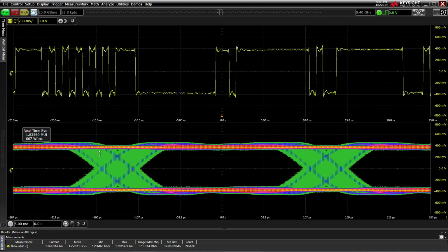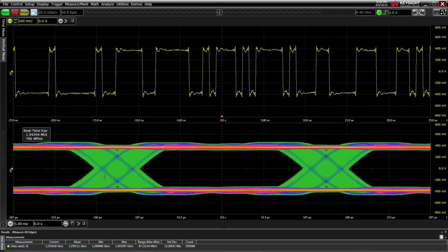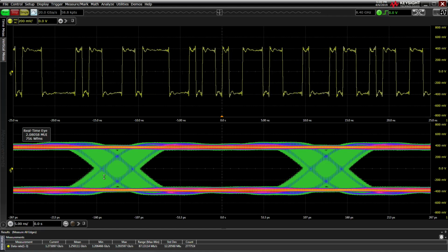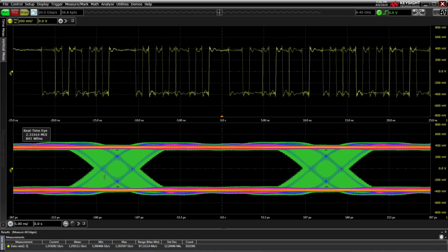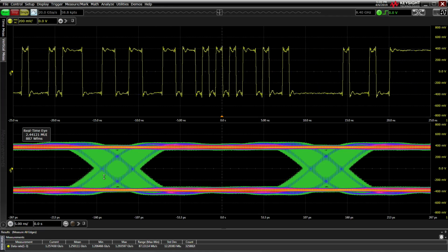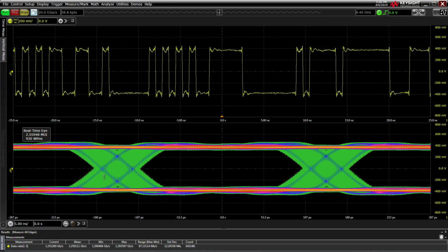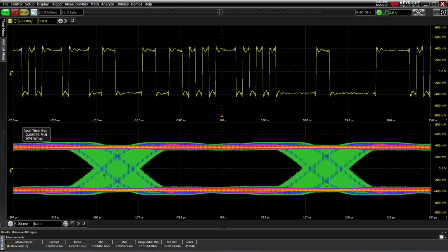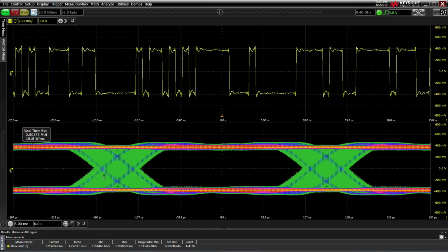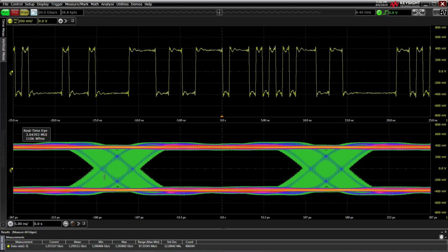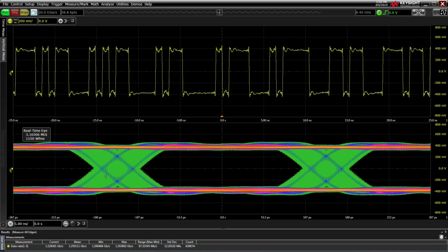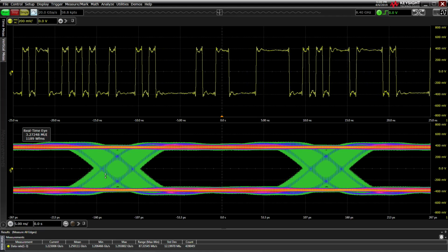But you can clearly see that the jitter can be applied to the signal, and this is a very useful tool to stress clock and data recovery systems to see how they react when they have a particular jitter composition. You don't have to put a square wave, of course, you can put any waveform you want, and that's going to be directly translated to the jitter frequency content. So that part works. I think at this point we should go back to the instrument and see if the error detector works, because a lot of the functions of the transmitter seem to be working just fine.